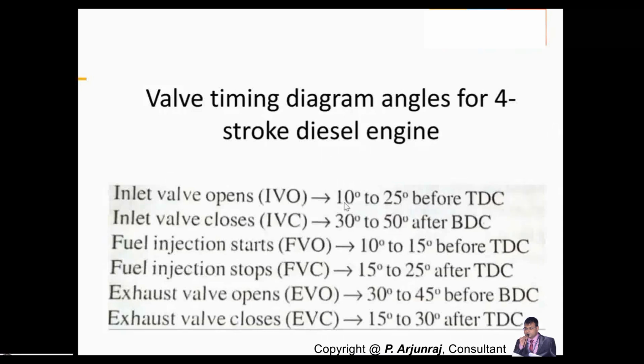And the inlet valve is closing between 30 to 40 degrees. It can happen at either 30 degrees or 50 degrees, and that is going to happen after BDC. And again, the fuel injection is going to start. I told you this is happening during the compression stroke, and that is going to happen before the top dead center of the cylinder. And during the power stroke, the fuel injection is going to stop.